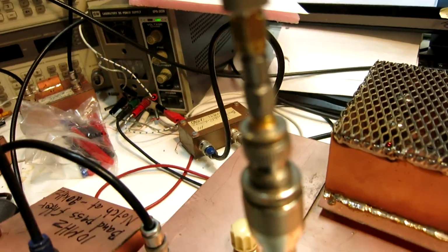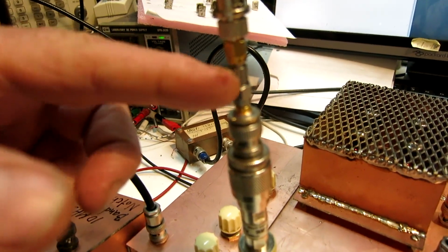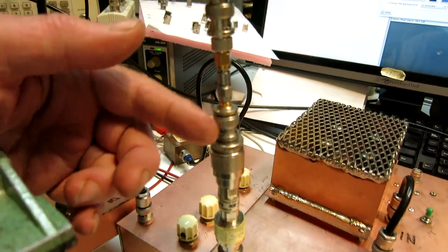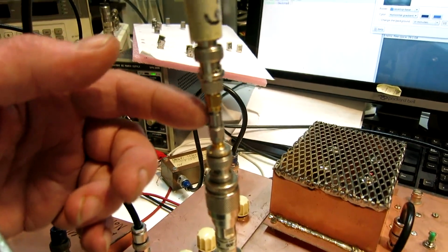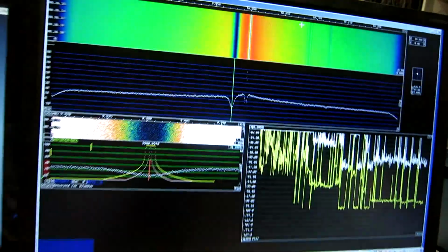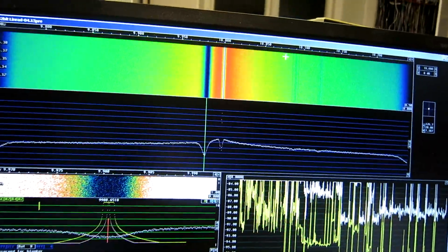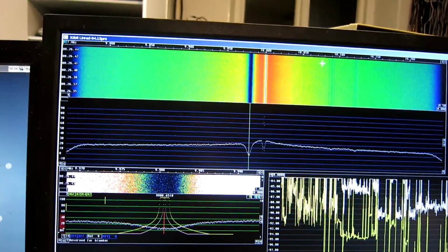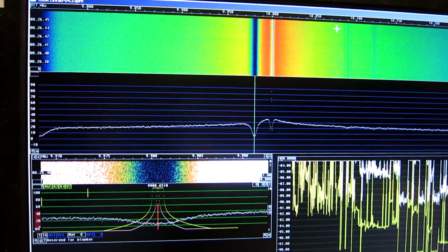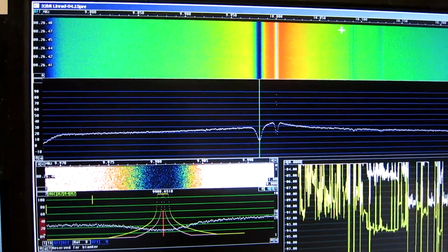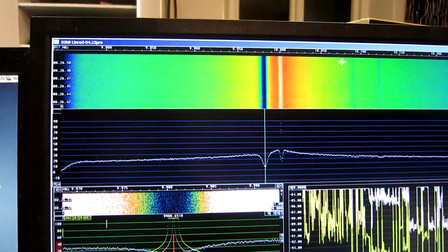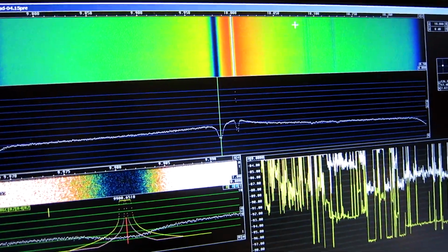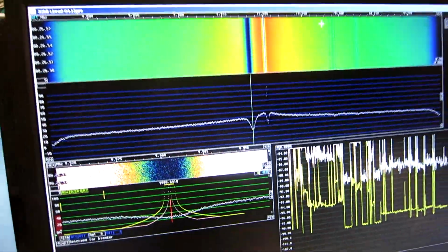I have inserted now this 3 dB attenuator at a power level of 0.5 watts, and it's rated well above that. And what I see on the screen is this. In the notch, the noise hasn't increased, but outside the notch, the noise has increased dramatically. This attenuator produces severe sideband noise. It's probably AM noise.